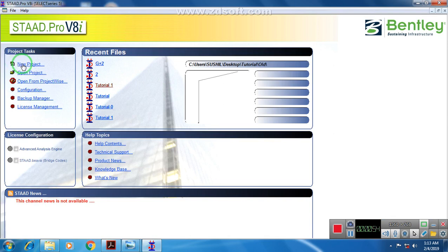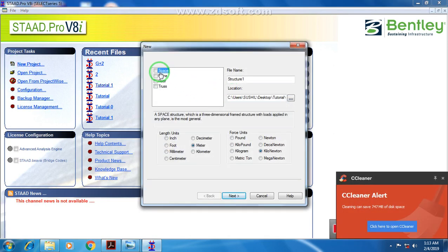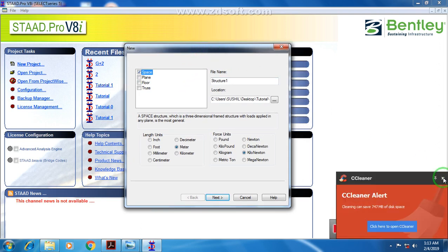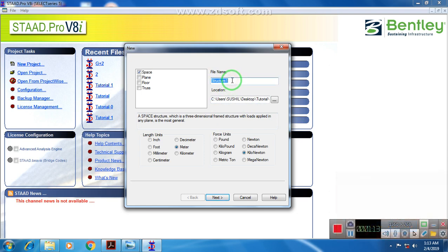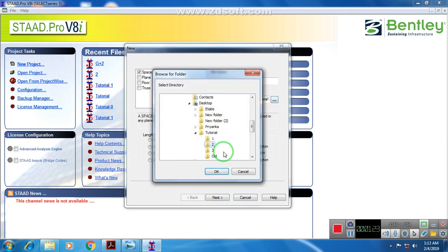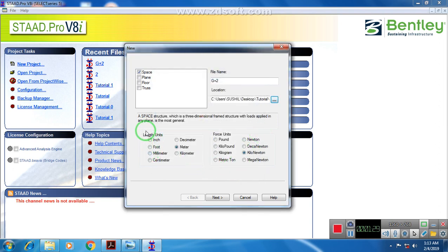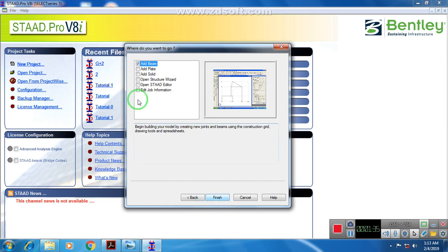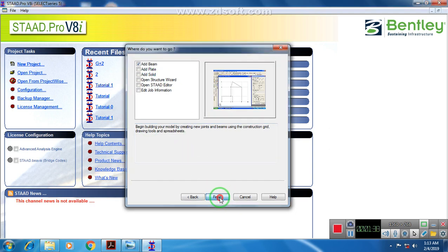So let's create a new project. Click on new project, then click on space. Guys, in my last video I explained all these things, how to make geometry. So if you have not seen it, please go and watch my last video. Let's name it G+2 and save it in a folder. I am saving it in this folder. Click OK. This is the length unit and this is the force unit. So click on next, add beam, then finish.